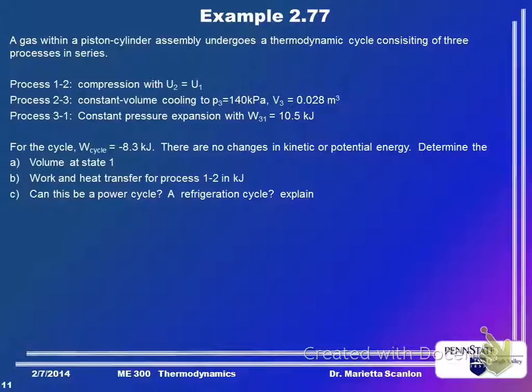Okay, so here's a good example of where you're not just given values for your property chart, you're given values for your first law chart as well. So when you start constructing the solution, put a property chart and a first law chart and fill in the knowns and then work from there. Okay.